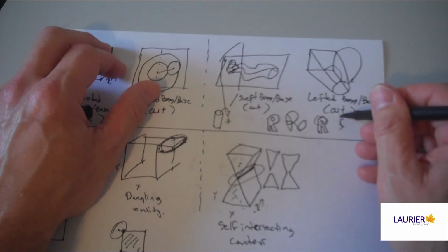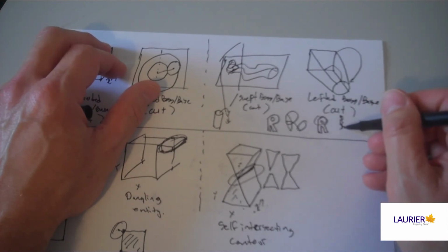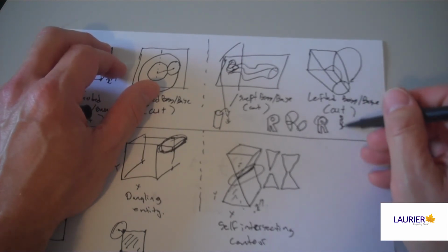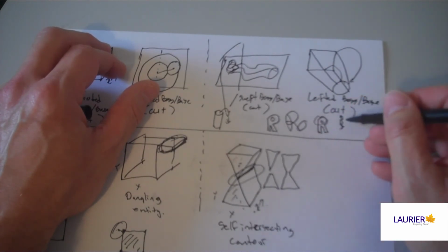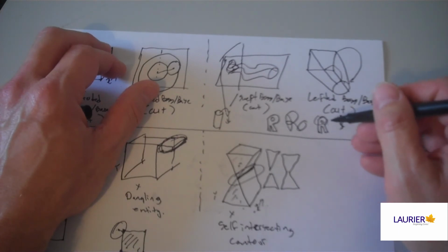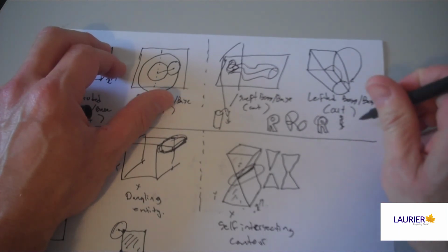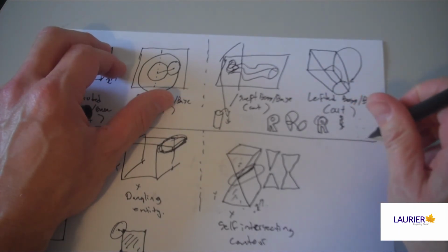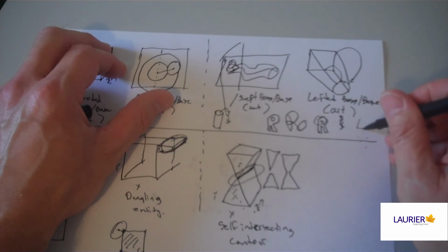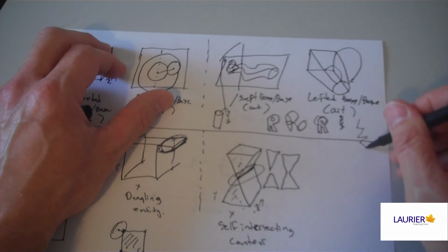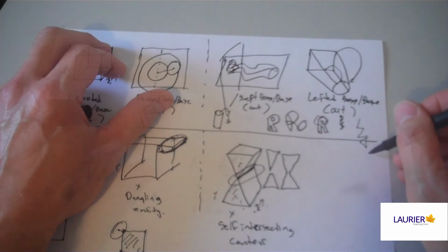So what happened there? Well, some fonts are made up from hand-drawn fonts that were scanned in. When you scan something in, it picks up a series of points called rasters, and then it puts it through a vectorizing software, which ties all the points together with a series of straight lines. Doesn't always get them in a linear fashion, and that's where you can get this messy line work. These can be fixed if you've got a font that you really like, but it's very time-consuming.